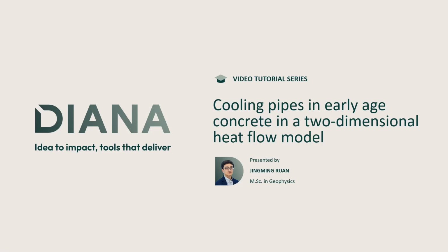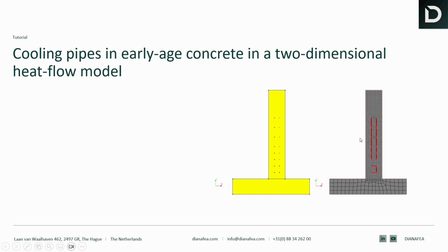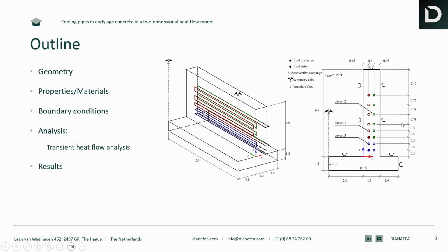Today I'm going to introduce a tutorial called cooling pipe in early age concrete in a two-dimensional heat flow model. In this tutorial I will explain how to do a 2D heat flow simulation in Diana considering cooling pipes. So this is the geometry of this tutorial.